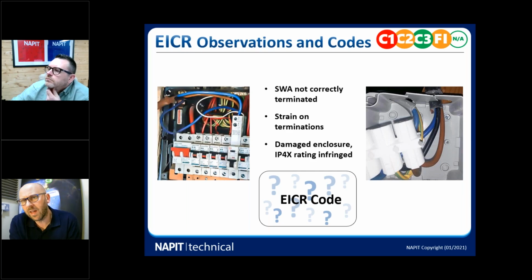You'll notice there's a spare strand in the SWA conductor that's just left there floating, cut off. That's not really best practice because you can get induced voltage onto spare strands. So if you get spare strands, they need to have a safe end on them, and quite often what used to be old practice would be to actually color code them green and yellow and put them down to earth. I don't know if that's a practice that we still see today.